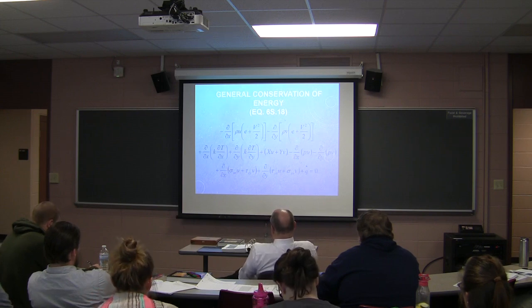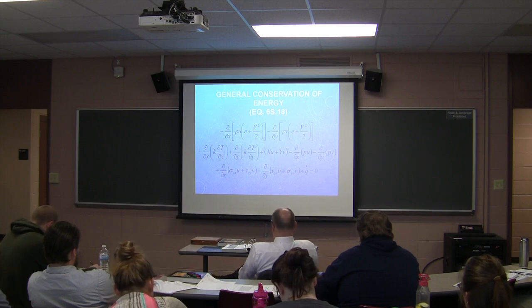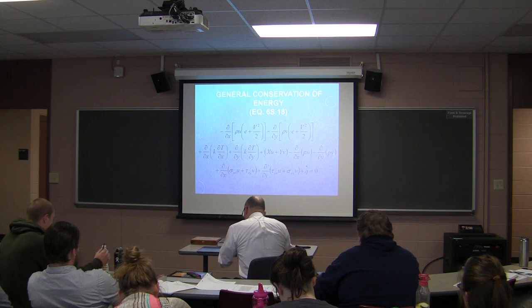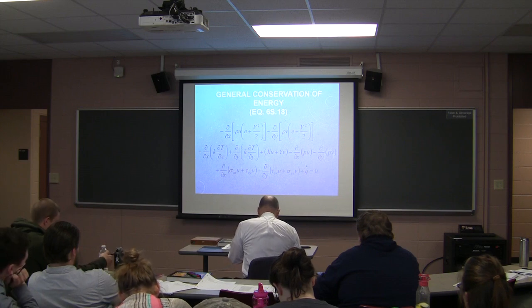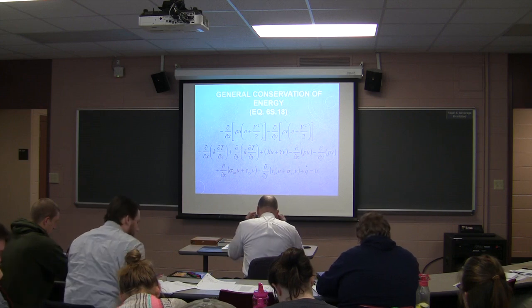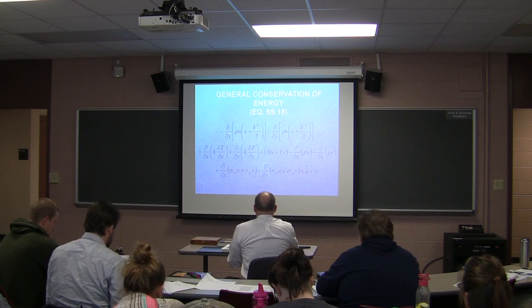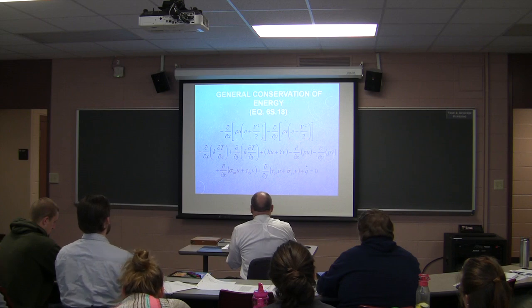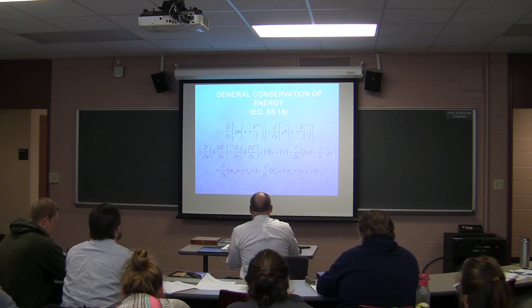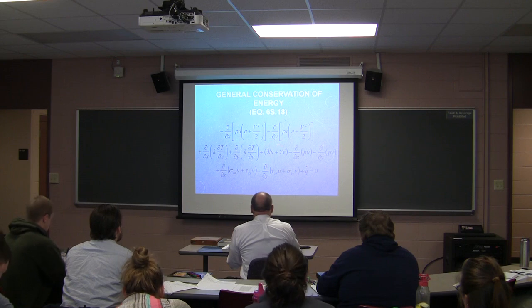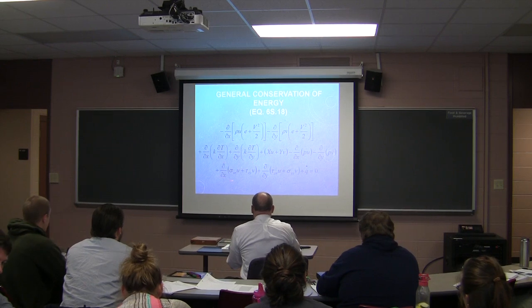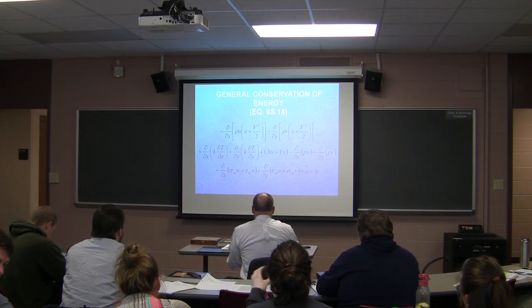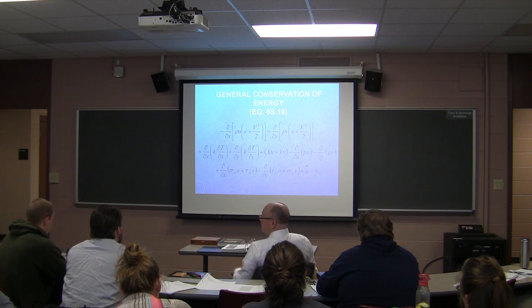Then we put the whole thing together, in 2 dimensions. And this is based on the figure, I don't know if I have it down here. Let's look at the terms for a moment. This term here is your advection term. This is your conduction term. These are your body forces. These are your pressure terms. These are your shear and normal stress terms. And this is your internal energy generation.